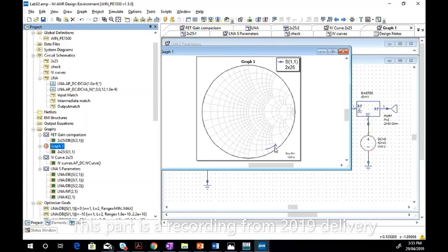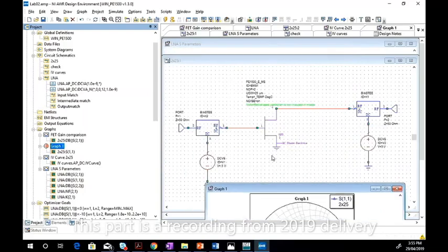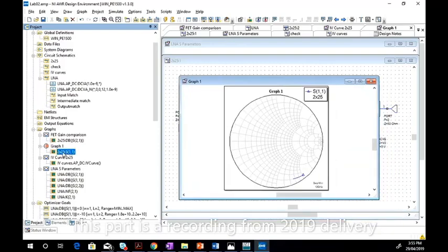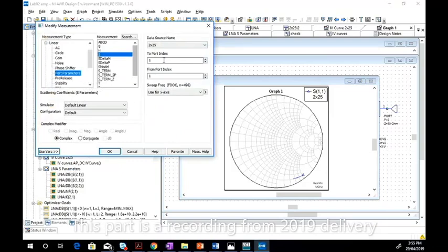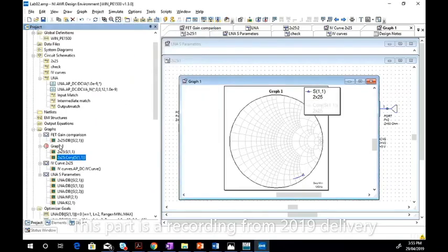So when I want to match the circuit here, whatever circuit I come up with will need to have the conjugate of that, right? Because then the imaginary parts will cancel out. So that means I have to plot the conjugate of this as well. When you want to plot the conjugate, you do that. So that's the conjugate, and it will be exactly on top of it.